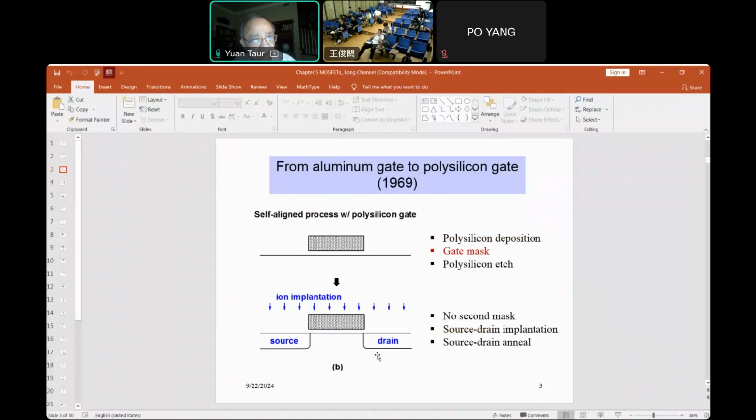But as I just mentioned the last hour, the polysilicon has to be replaced when the oxide is very thin because of the polysilicon depletion problem. So in the current process, it's using a metal gate. As Jack mentioned, it's the so-called replacement.